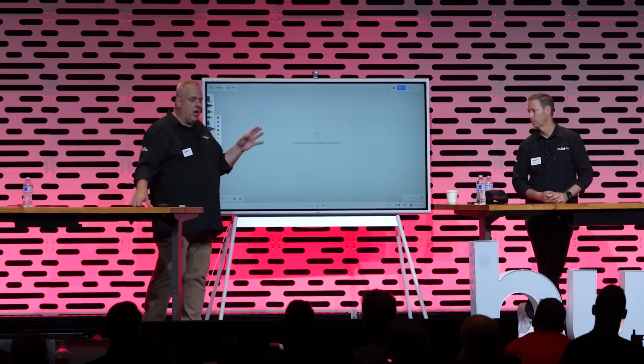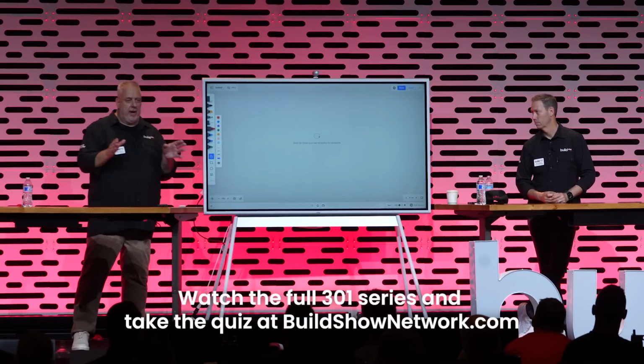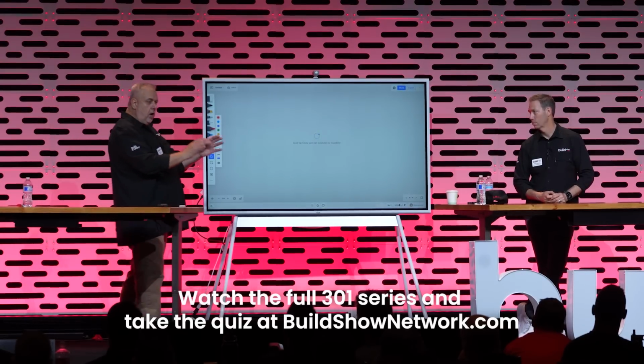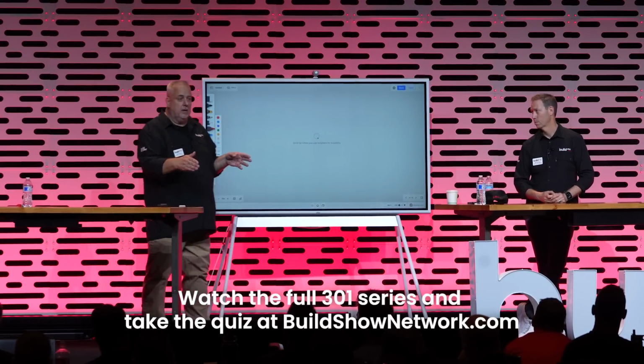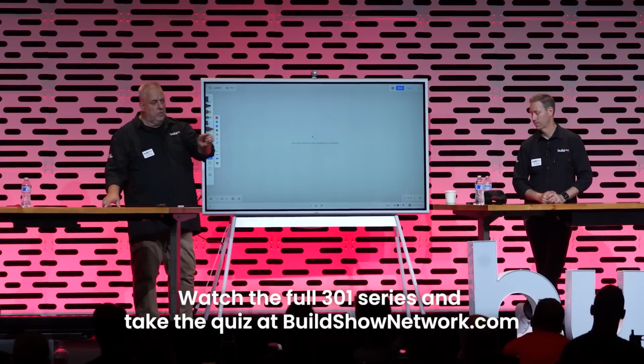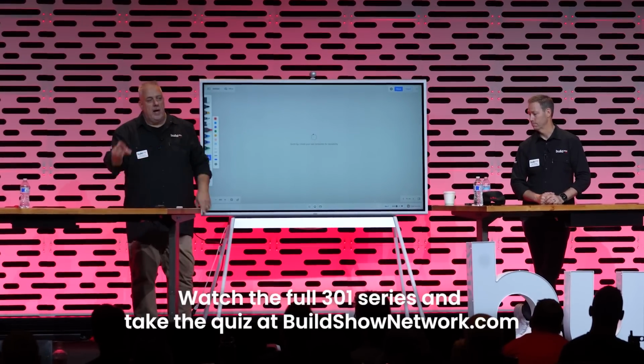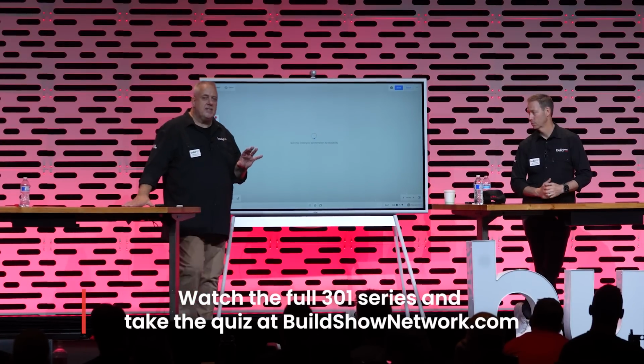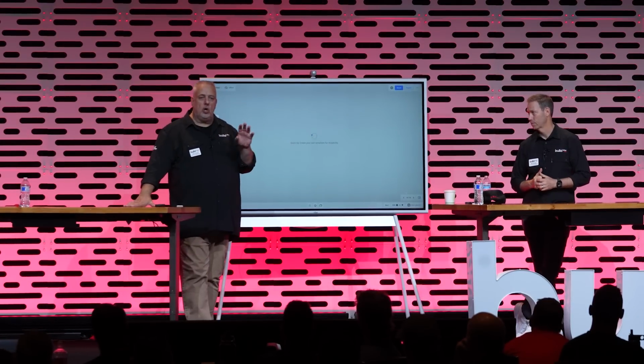But when you're here in Austin and you've paid for a nice 70-degree room or 72-degree room in your family room, and it's 101 outside, guess what's happening? Heat is trying to move across that assembly and warm that family room, right? Insulation, people, is not about heat or cooling. It's about energy transfer. It moves from hot to cold. That's why we call it R value, resistance.